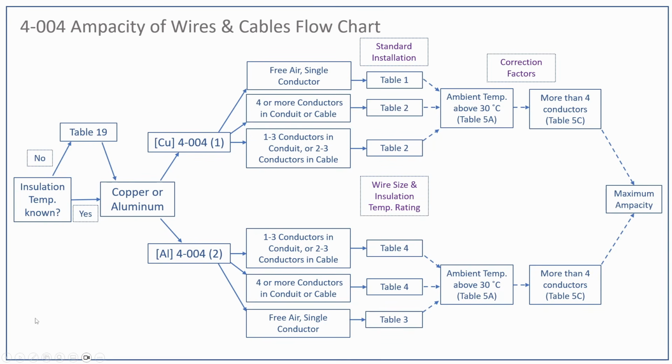and I'll show you a kind of flow chart that I've created here. The first thing we're going to look at is: is the insulation temperature known? We're going to do another video on table 19, but if we don't know the insulation temperature, then we're going to have to go to table 19. All of the examples that we're going to be given in this video are going to tell you the insulation temperature. So yes, we know our insulation temperature.